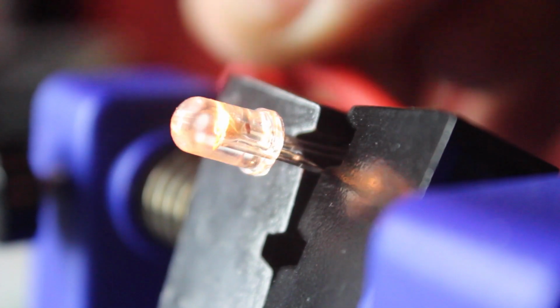So let's jump down the rabbit hole for a second and plan out a circuit. Let's go for something that we might have a little more readily available, like a 9-volt battery, right? We can get those at a store, so let's plan for that. If I put my same circuit with those resistors on a 9-volt battery, it's going to allow more current, and that's going to have the LED essentially burn itself out. So it's not ideal by any means. Not for longevity, not for safely installing in anything. Because an LED burning out, it's still burning out. Literally, it's catching fire inside the acrylic until it no longer conducts electricity.